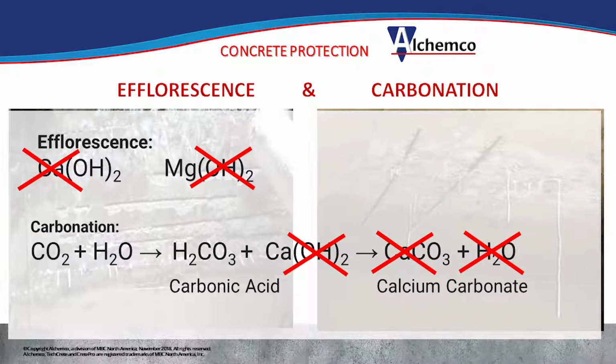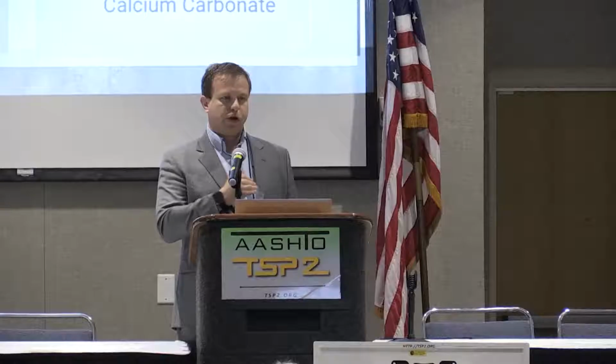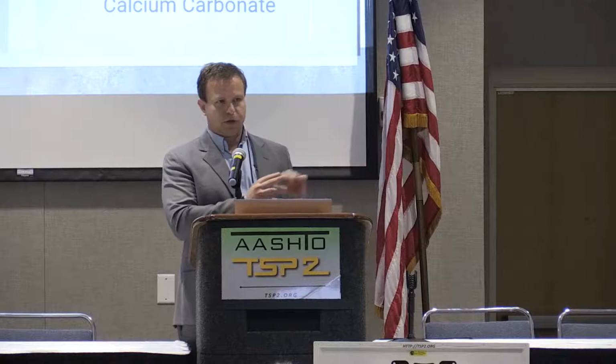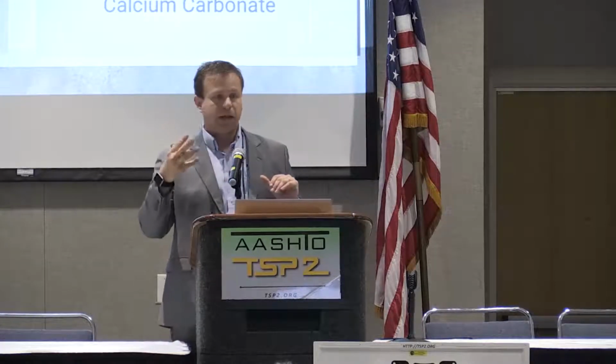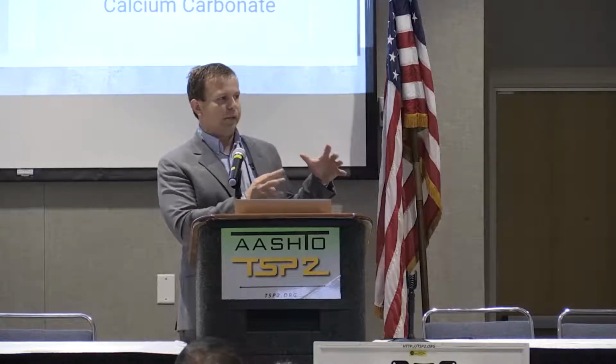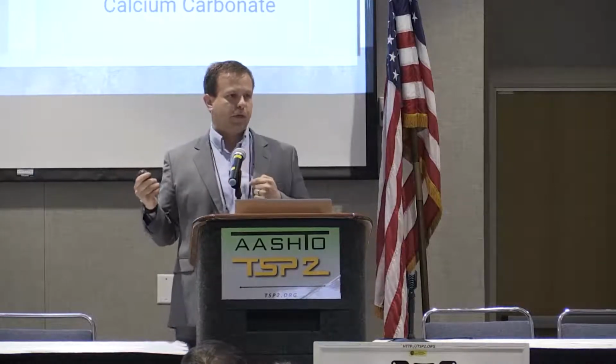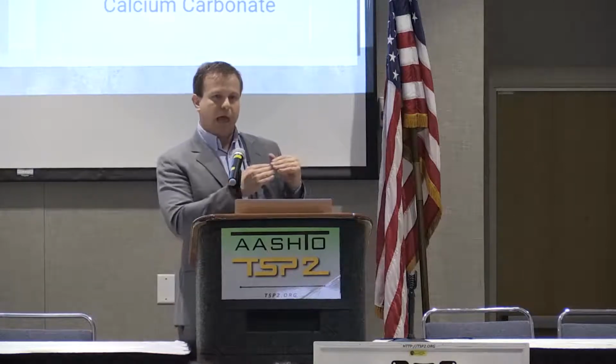The very first thing that this technology is going to do when it penetrates the concrete is to react with the free calcium, just like many other silicate materials. The very first reaction is that this material reacts with the free calcium. After this reaction happens, the next step is to form the flexible gel inside the structure. So this is the second step. The first step is we are reacting with the free calcium, so we don't have the free calcium. A lot of the issues that happen in the structure, now you don't have them, just because there's no free calcium available.